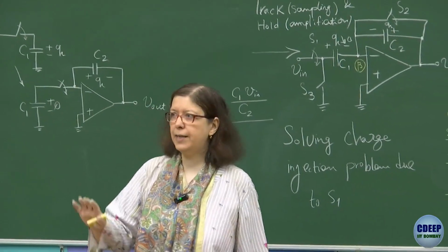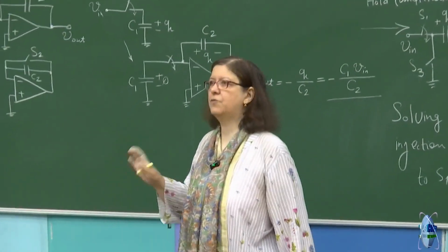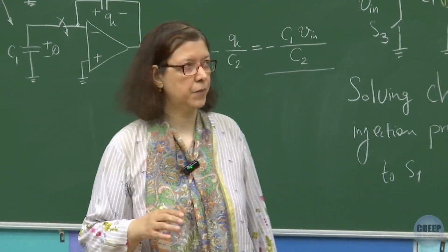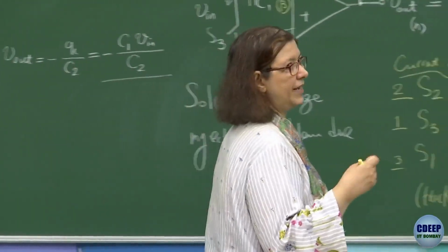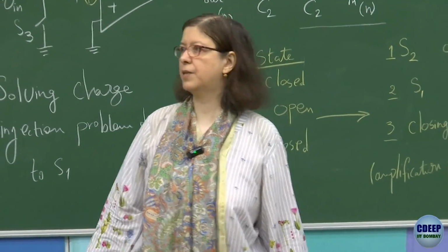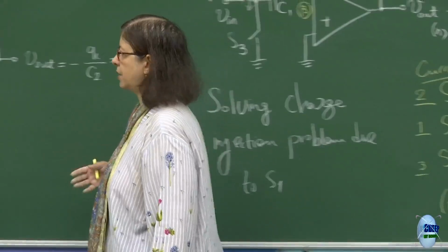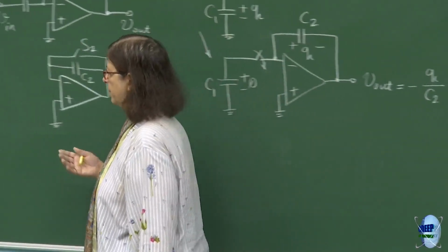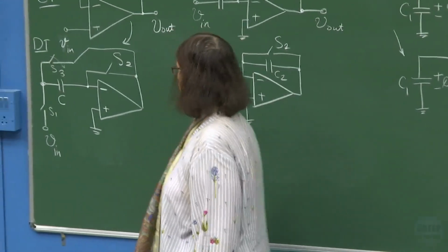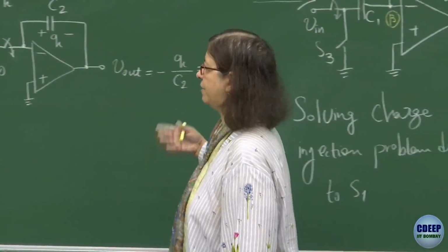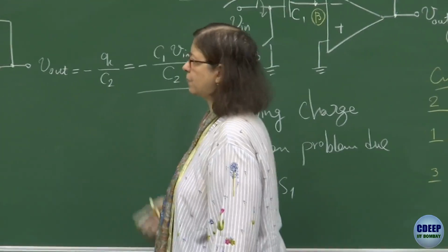So eventually we will not cover circuits which have the charge injection problem. We go with only bottom plate sampling or bottom plate driven configurations. It's bottom plate, sorry, switching. Bottom plate switching, I think, is a better name. So eventually we are switching it, or we are driven. We can say we can drive with ground, but yeah, it's better to call it switching.